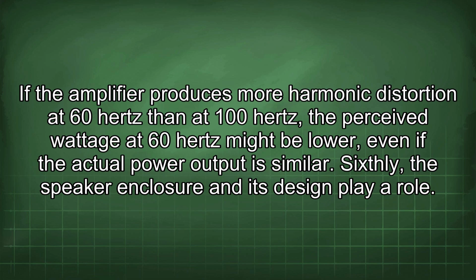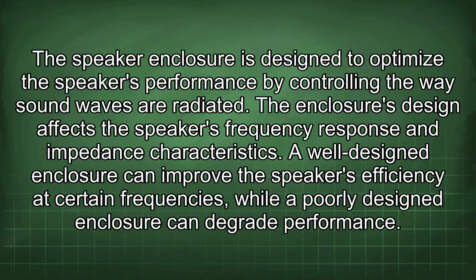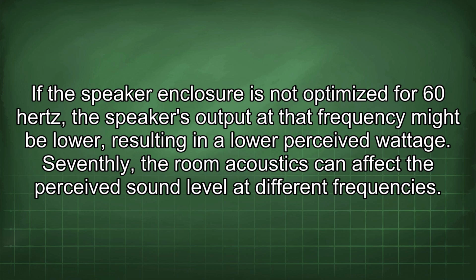Sixthly, the speaker enclosure and its design play a role. The speaker enclosure is designed to optimize the speaker's performance by controlling the way sound waves are radiated. The enclosure's design affects the speaker's frequency response and impedance characteristics. A well-designed enclosure can improve the speaker's efficiency at certain frequencies, while a poorly designed enclosure can degrade performance. If the speaker enclosure is not optimized for 60 Hz, the speaker's output at that frequency might be lower, resulting in a lower perceived wattage.